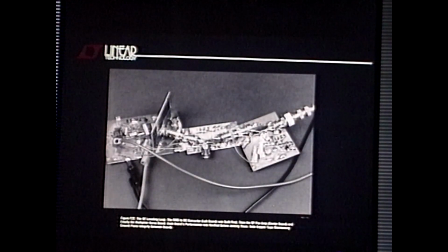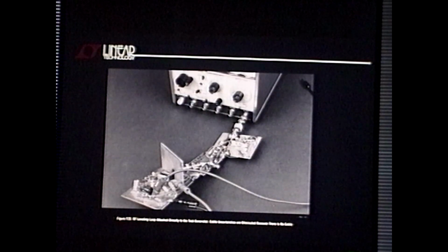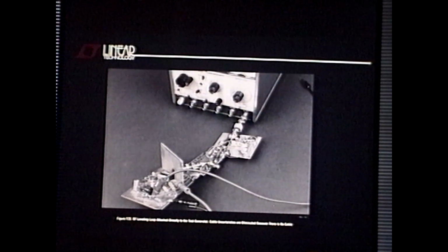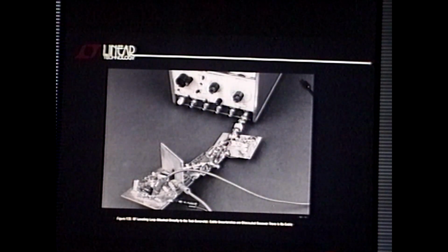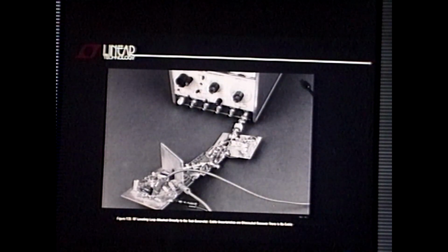The other thing you'll notice, when you're trying to measure something like this at the speeds this thing was running at, this is reversed. This is RMS to DC, so the scope doesn't have to look very fancy, but the generator generates the RMS test signal. I don't trust cable effects when I'm trying to measure something like this. So this is AC going in, terminated right at the generator, and I bolt the breadboard right to the generator. I trust the flatness of the generator. I don't want to have to worry about 3 or 4 feet of cable plus terminator.